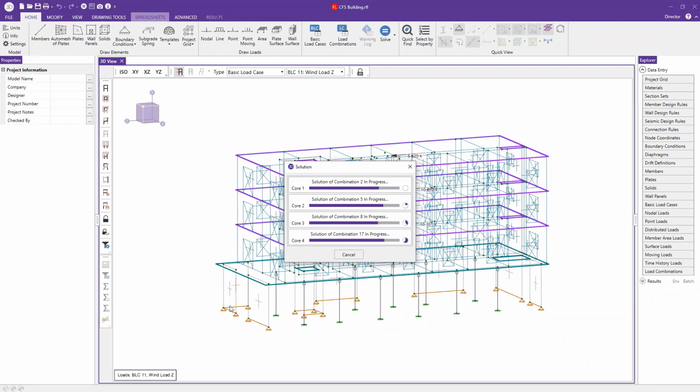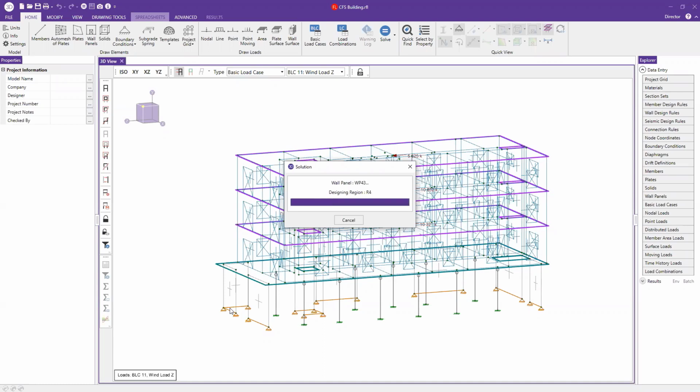Load combinations were thought through by me because we have a load combination generator that does it for you quick, but you do have different elements. So I have concrete and I have cold form steel, and I've decided to use ASD design of those cold form steel walls, and the concrete obviously is LRFD. So it's two different things happening on that. So you kind of want to make sure you've actually done that in that way.